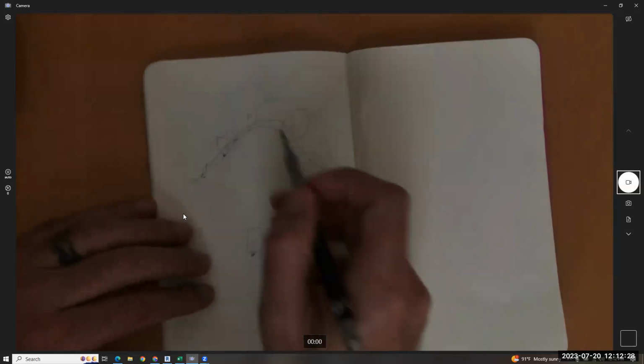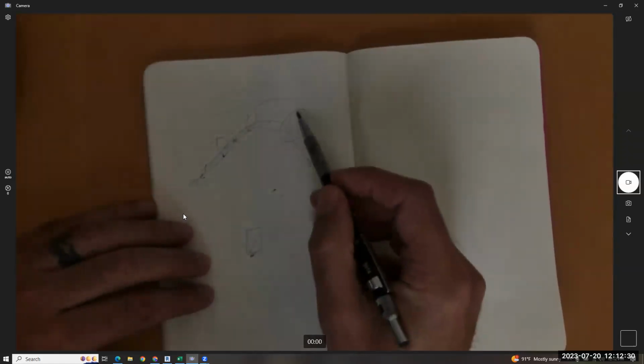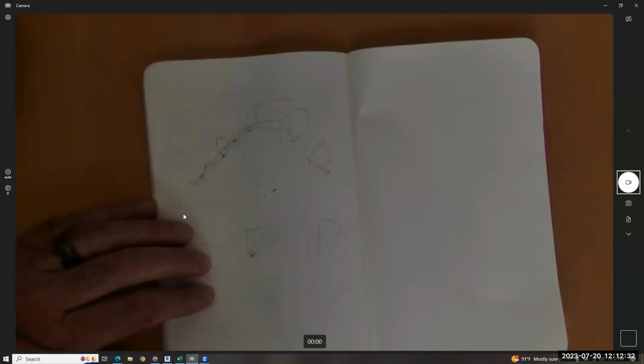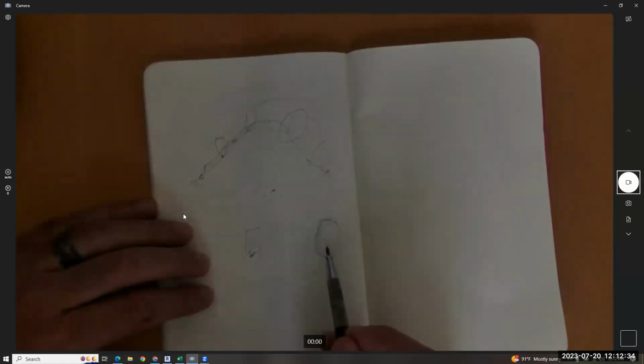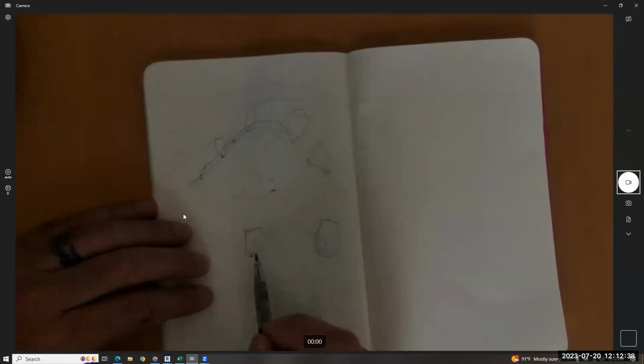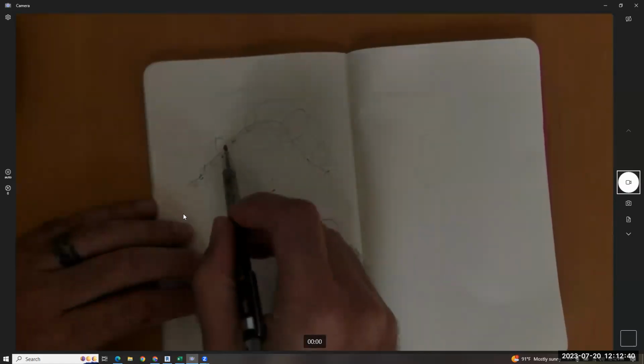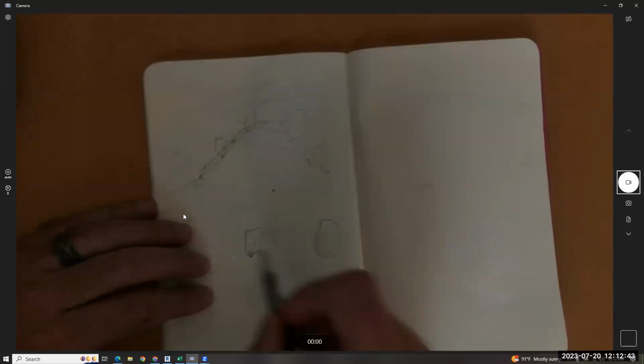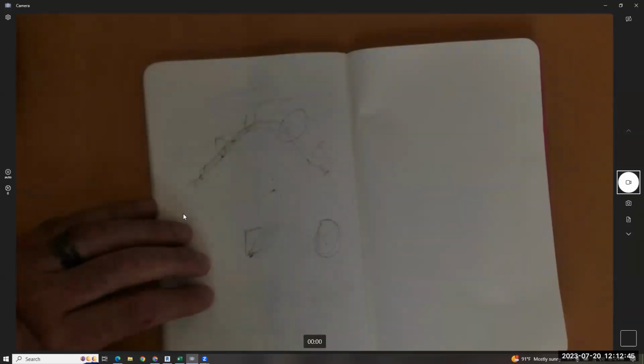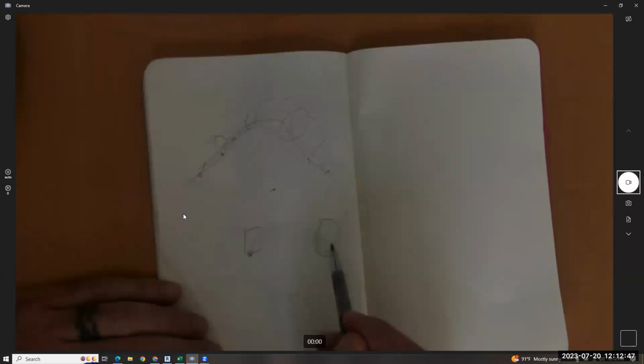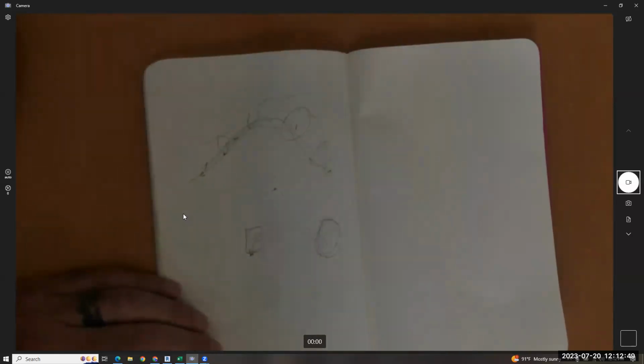You can also set this to where you have a reporting parameter and have that shape change based on another point, but it means drawing the profile in the profile, loading the profile into generic model adaptive, loading that generic model adaptive onto stuff. It's crazy, but you can get super complex forms that are reactive. That's 3 files just to get this.